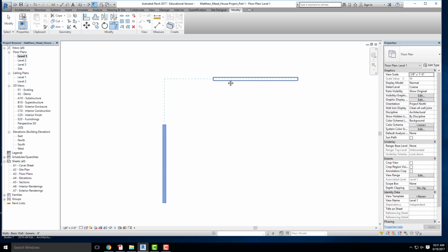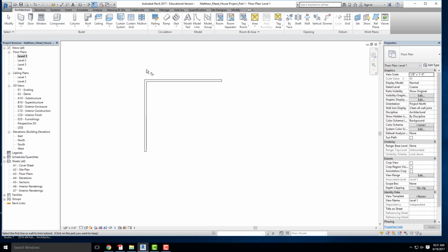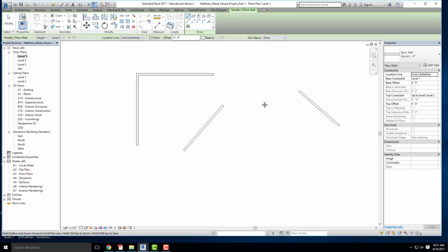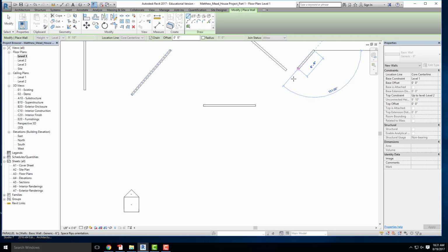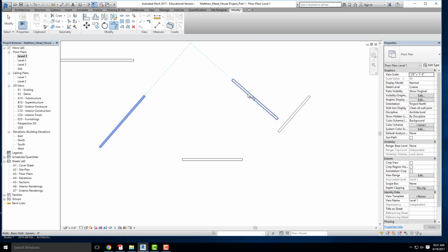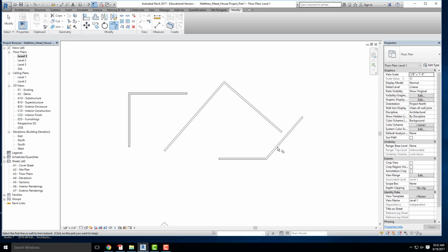So that's going to be the trim extend corner command, and they don't have to be in a 90-degree fashion. It could be something like this, maybe it's something like this. You can simply click on the 2 different walls that you want to extend and trim the corner, and it will bring them together in a perfect fashion. See how that works? So that's going to be our trim extend corner command.